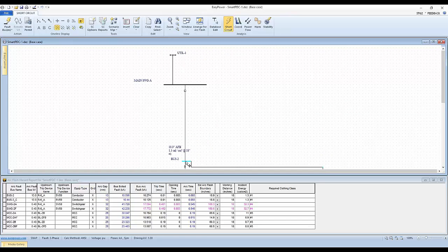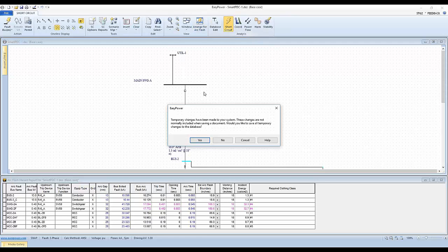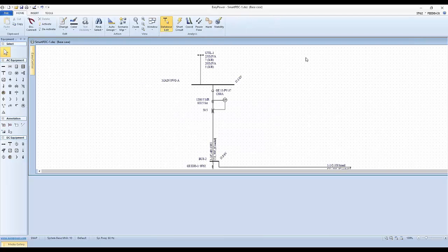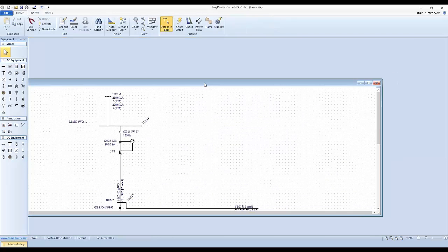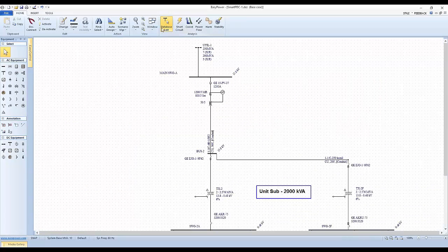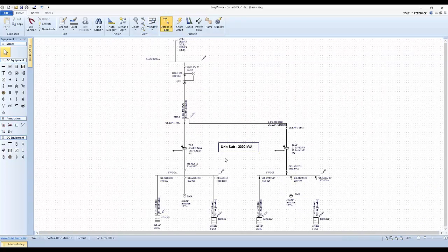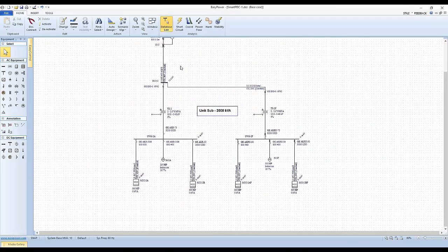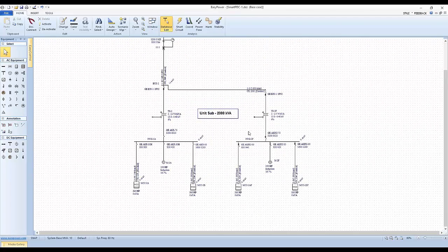So what we're doing is essentially manipulating the local settings for main switchgear A, so it'll either show up, not show up, or have specific time settings for the incident energy calculations. So let's go back to the parade rest here. All right, so that's how I handle each of the local buses when I know there's an exception.